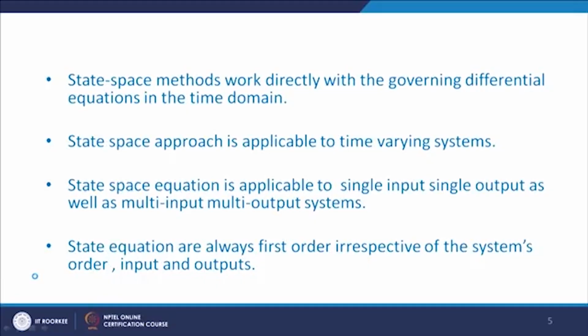Classical approach is based on the transfer function approach, and you know that in the transfer function we have to neglect the initial conditions. Whereas if you go for a state space approach, we can consider the initial conditions. Third, state space methods work directly with the governing differential equation in the time domain. As I told earlier also, state space approach is basically based on time domain, and classical approach is based on S domain or a frequency domain.